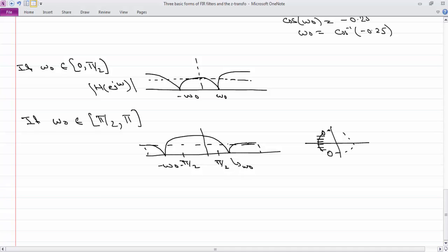So these are three basic types of FIR filters. Of course, you can have an FIR filter which is neither a low pass nor a high pass nor a notch filter, and then, if you want to design FIR filters using pole zero diagrams, the only thing you have is the location of zeros, and what you can do is move the zeros around. For example, just open MATLAB and place zeros at different locations till you are satisfied with the frequency response that you are looking at. And then you simply write down your impulse response using that transfer function.